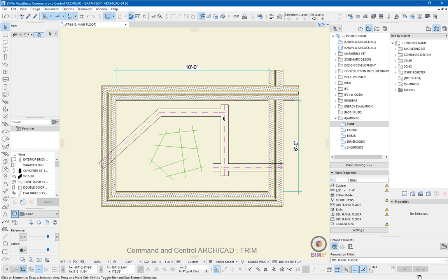So in this case it's trimming away there. If I control click in the middle, then you'll see what it does is it trims to the two nearest points. So in terms of these lines, I could either trim away the middle pieces, or we could come in and tidy up these ends. And literally all I'm doing is holding down the control key and clicking to trim away.